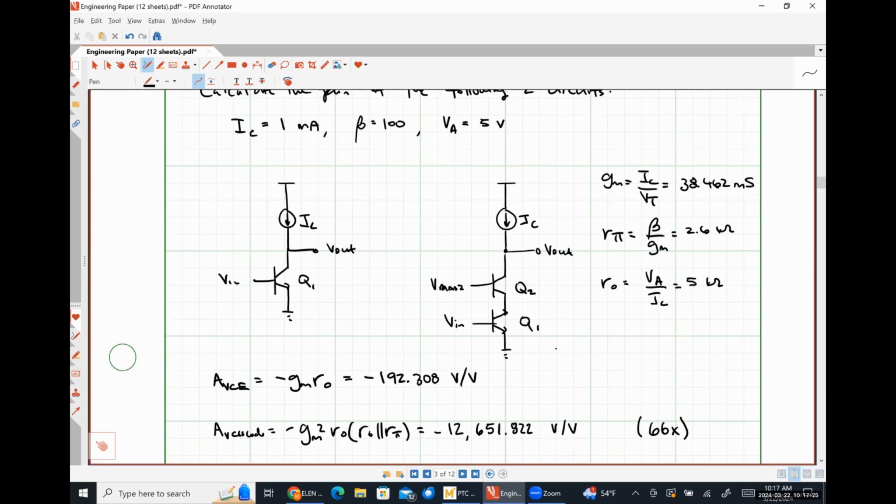So we're looking at all of this stuff on a small signal level, right? Large signal, every transistor that we stack on top is another DC voltage that we have to make sure keeps that transistor operating in, for these BJTs, the forward active region, which means we need a VCE greater than the VBE that's biasing it and all of that kind of good stuff.